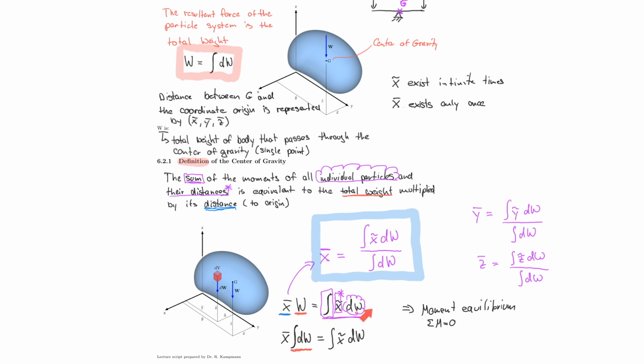What we need to understand to get to this point is that we have a balancing equation here, the sum of the moments. For now, I can just tell you that any point in space needs to balance like this equation says. We are just choosing to do it over the origin, because that will clearly define our x bar for us, and that is what we as engineers will be interested in. So that concludes the center of gravity. And now I will show you very quickly how this applies to the center of mass and the centroid.